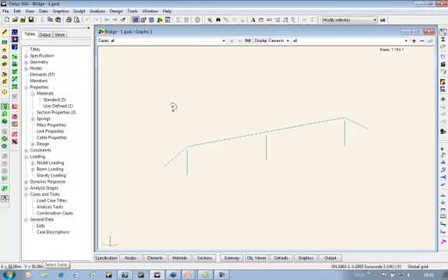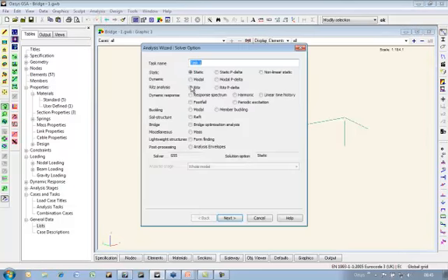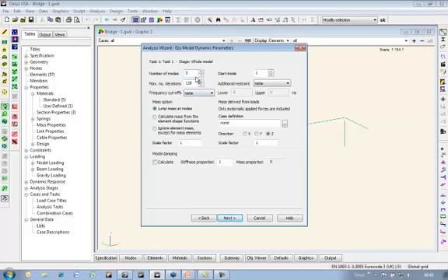And what I'll do here, I will run some analysis. Now I know from checking previously that 3 modes will be sufficient for this. Self-weight is all in there already. Bridges, staircases might not take any live load. I'll choose not to in this case, so maybe just 1 or 2 people walking across.